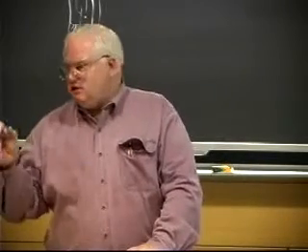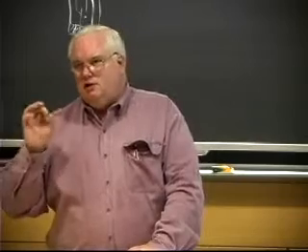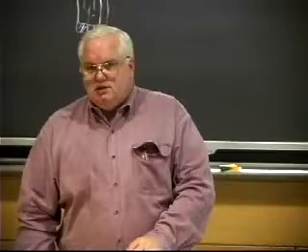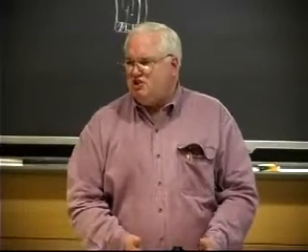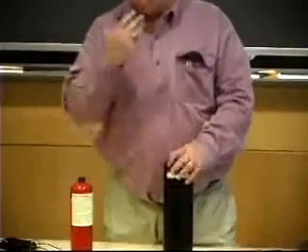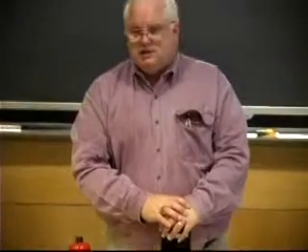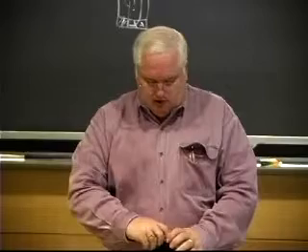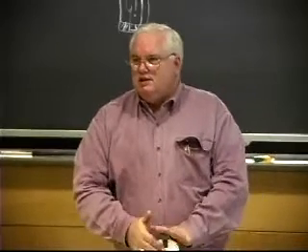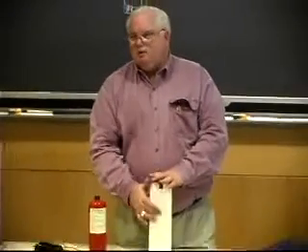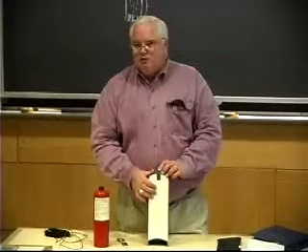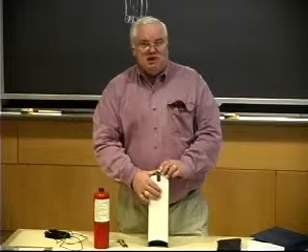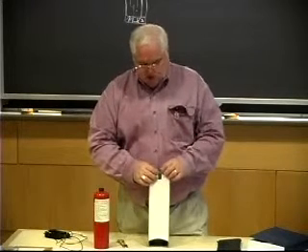Doesn't matter what the size of the tip is, they designed it so the incoming acetylene should be at 3 to 5 psi. This is an acetylene cylinder, but you're not just storing gas here at 10 psi because you'd have all of about 60 seconds worth of gas used out of a cylinder like this. It turns out an acetylene cylinder, if you look inside, is actually filled with a very porous material, in this case a white material, which is calcium silicate. It's about 92% porous.